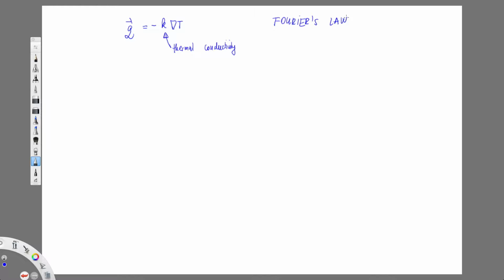So now I have a fluid, and there is a difference in temperature within my fluid. Is Fourier's law enough to describe what will happen as a result of that temperature gradient? So what else do I need? Fourier's law is essentially enough for a solid. I have a solid, I basically know pretty much everything that is going on based on this flux. But now I have to add the fact that in a fluid, I also possibly have a moving fluid. If there's no velocity, then again, Fourier's law is enough.